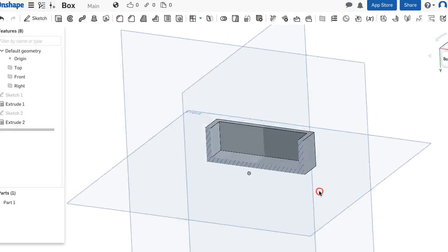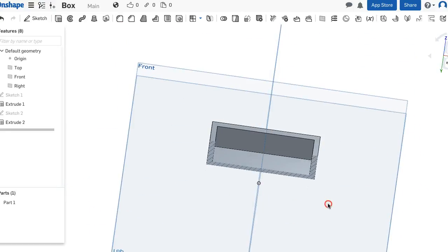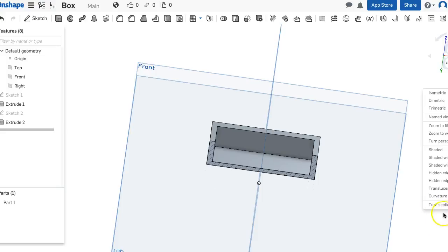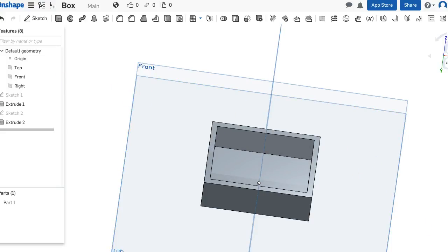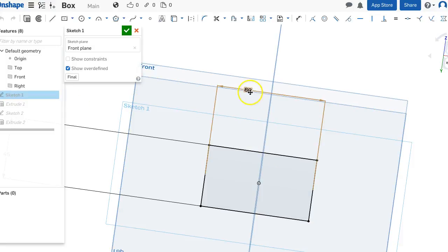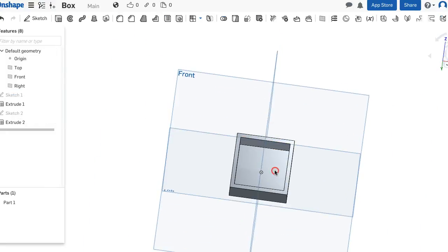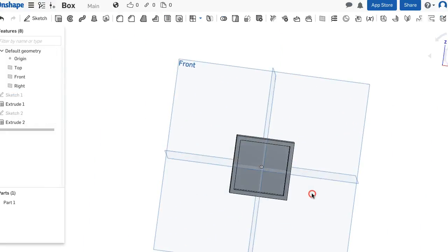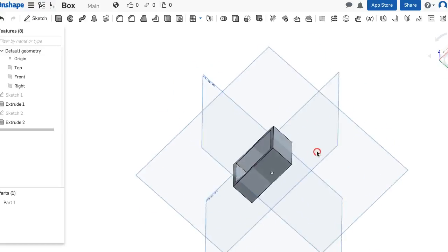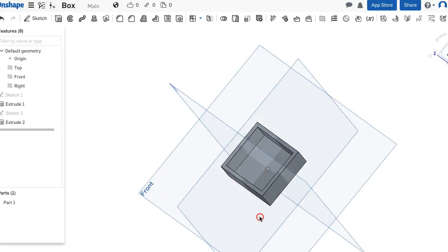Now I don't know what happens if I make it less than 3, but this is kind of the power of this parametric modeling. I can also go back to this first sketch, and I can say, you know what, I only want this box to be 45 millimeters in that direction. So I press enter and check, and now it made the box skinnier. I still have my 3 millimeter offsets though. And so now I've made a box, but I'm not done yet.